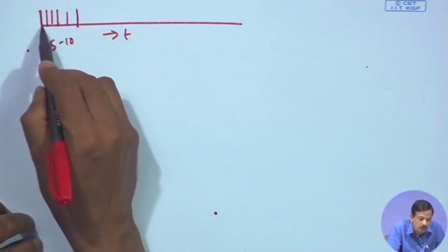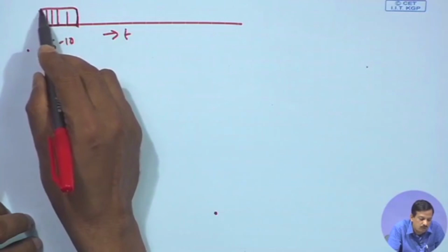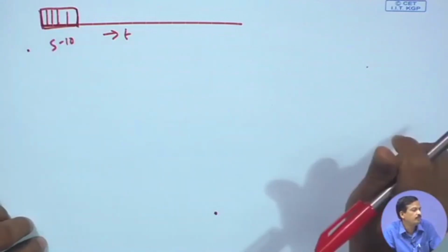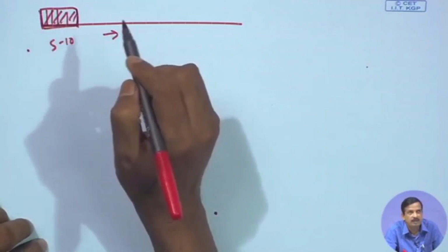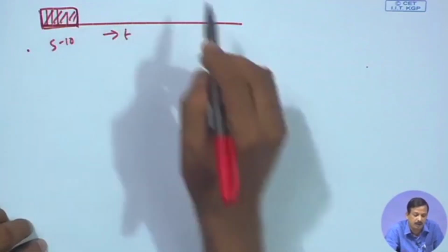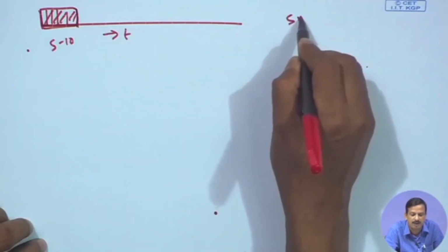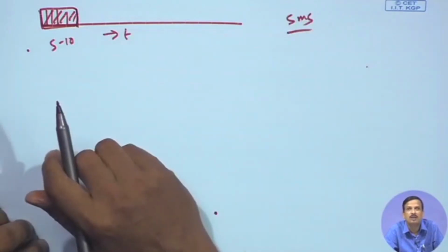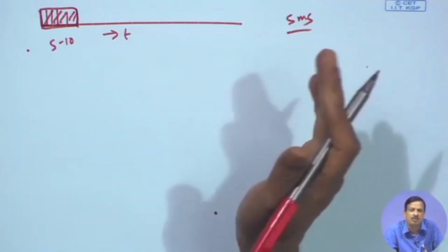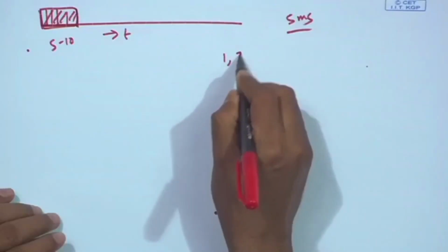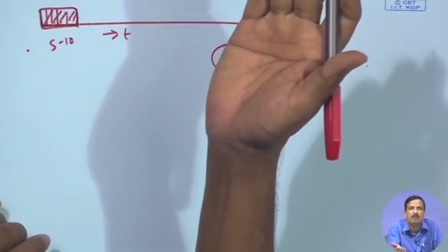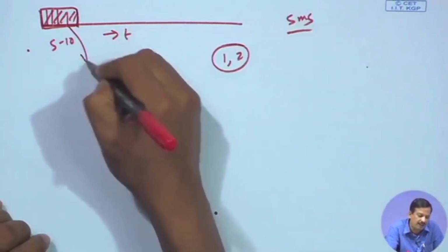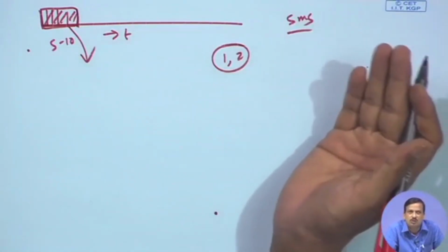For a 5 to 10 millisecond window, it is a very short signal. Due to the small amount of data, now if you see the pitch, let us say I have taken a 5 millisecond window. It may be found that within 5 millisecond, maybe 1 or 2 fundamental periods are there. If it is a male voice, then maybe 1.5 fundamental periods are there. So, if I analyze it, it is of no use.